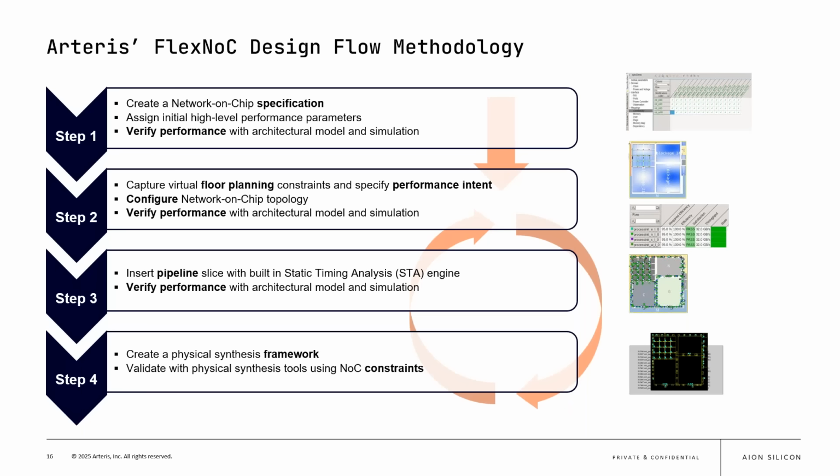So we see here that FlexNoC 5 brings a physically aware design flow that ties the NoC topology directly into the system on chip floor plan. So instead of building the interconnect and hoping it fits, we actually align sockets, paths, and pipelines with real physical distances.